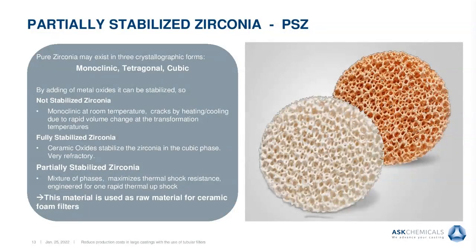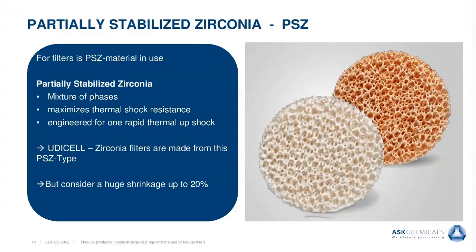As mentioned, the best ceramic material used for filtering high-temperature steel and iron-based alloys is partially stabilized zirconia, utilizing magnesium oxide as a stabilizing agent. This material exhibits excellent thermal shock resistance, as I described already, and furthermore has very good chemical, mechanical, and thermal ruggedness.